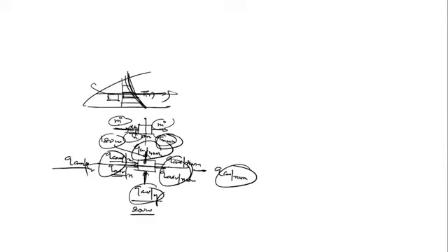So, dear student, if you solve this equation, then you find the temperature distribution. And you might have got some information that in advection we must write m dot cp. What is Q advection? m dot cp into T, and this mass rate involves the velocity. So can you say that the temperature distribution can't be solved without knowing the velocity distribution? You are never supposed to solve the energy balance without solving the momentum equation, the momentum balance.